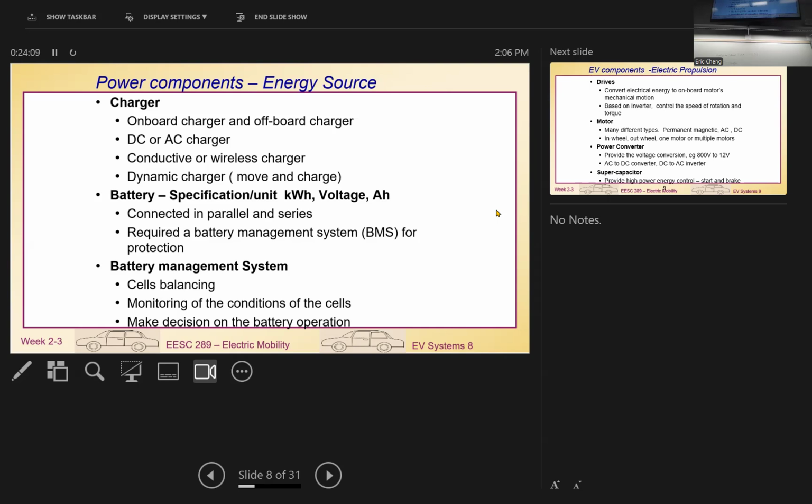So recently they want like 90.4% efficiency for transmission. That's true. You see, the international standard controlled by SAE will be at least 85%. So that means if you make anything less than 85, you can't sell in the market. But 85 is quite good, really nice. Usually many people do not believe wireless charging can go up to 85, but that became a standard, which means many people are doing it. And with a separation of 15 centimeters, that's quite a distance between the two coils. So that's what we're trying to think about.